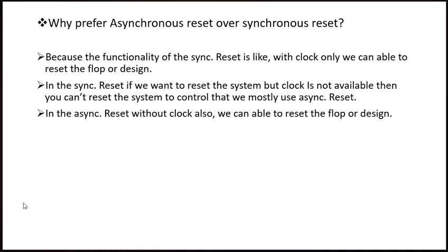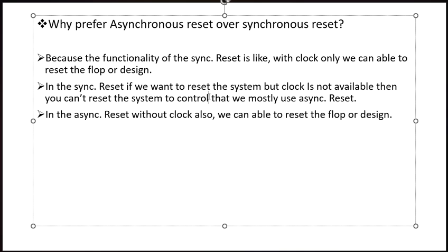If something happens to my design, like it is not properly driving the clock or my system has hung because the clock is not going properly, then, since a synchronous reset works only with the clock, we can't reset the system without a clock. If my design is hung and my clock is not driving properly, the synchronous reset can't work, because to give output it needs the next clock edge.